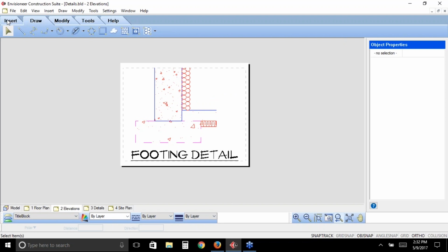And using our Insert pull-down menu, Import a CAD file tool, you could bring that back in on all of your future projects. So you could save them strategically somewhere out on your hard drive, all of these details that you've exported, and then just import them into your new projects by using the Import CAD file. I'm going to go over that tool in just a minute.